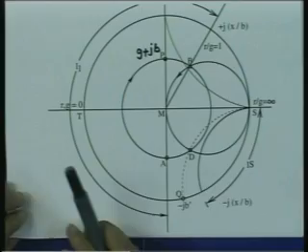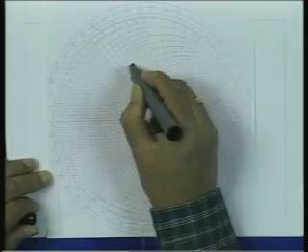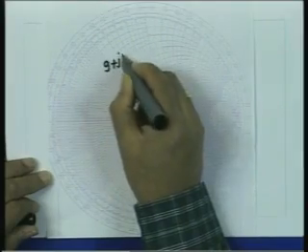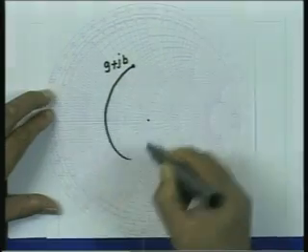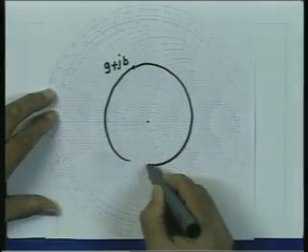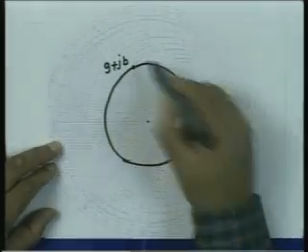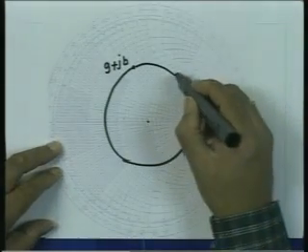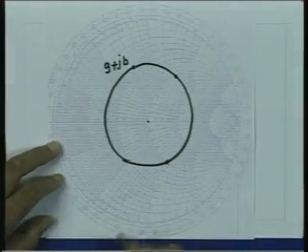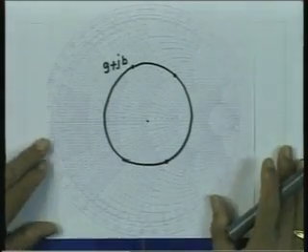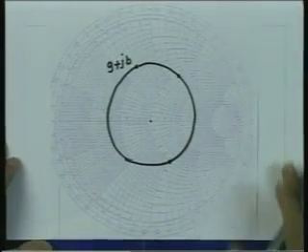Okay. Now, let us do this exercise. So, let me take this Smith chart and do that. So, this is my Smith chart. Let us say this point marked is P, which is G plus JB. I draw a constant conductance circle passing through this point. This is the unity circle. So, at this point here or this point here, the conductive part of the admittance has become equal to 1.